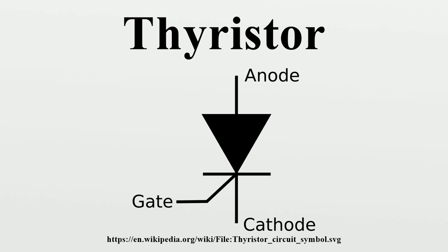Comparisons to other devices. The functional drawback of a thyristor is that, like a diode, it only conducts in one direction. A similar self-latching 5-layer device, called a triac, is able to work in both directions. This added capability, though, also can become a shortfall, because the triac can conduct in both directions. Reactive loads can cause it to fail to turn off during the zero-voltage instant of the AC power cycle. Because of this, use of TRIACs with heavily inductive motor loads usually requires the use of a snubber circuit around the triac to ensure that it will turn off with each half cycle of mains power.